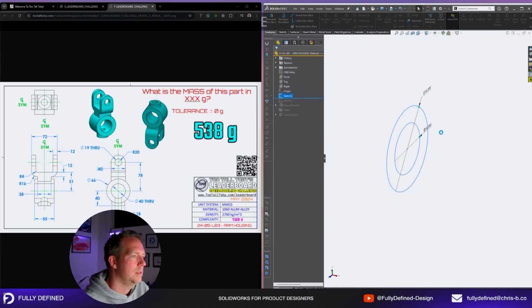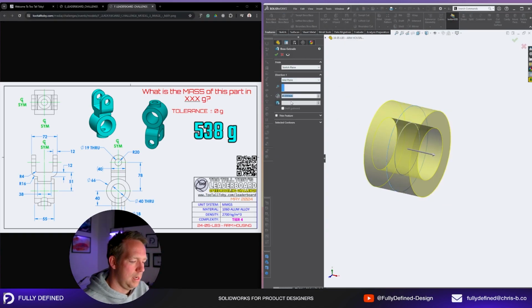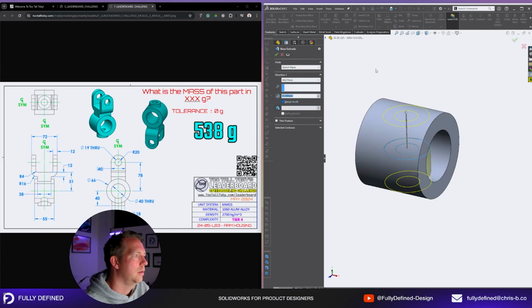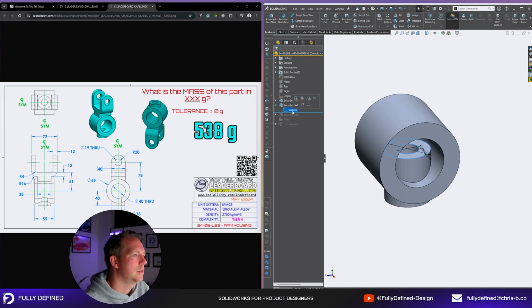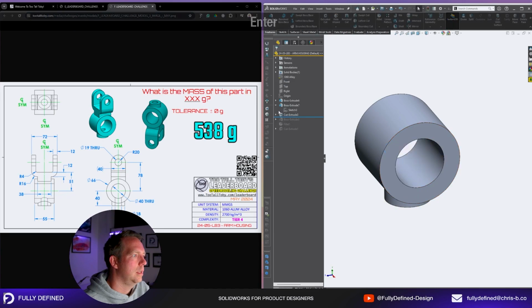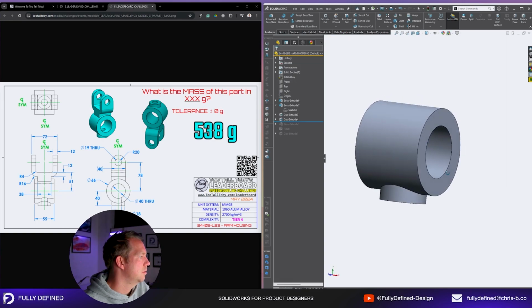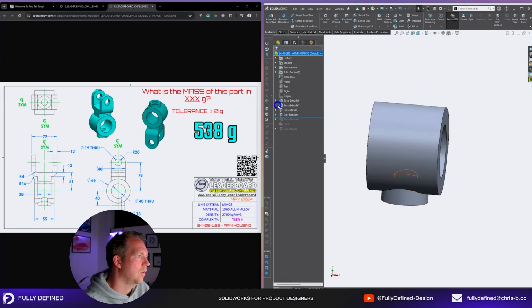So that means we'd start with this one. We go mid-plane, 55, and then we've got our second sketch, and we're doing a few things. We're going 40 down. Next we are up to surface. And then last, we're going to cut through all. Just got to make sure we're doing the right selections. But that is pretty quick. It's just we've got 4 features.